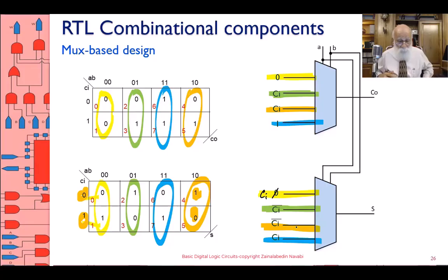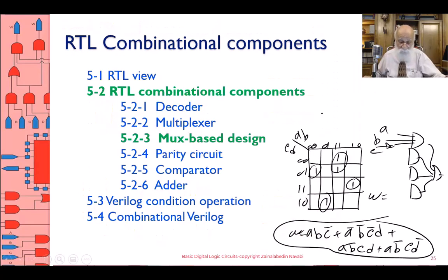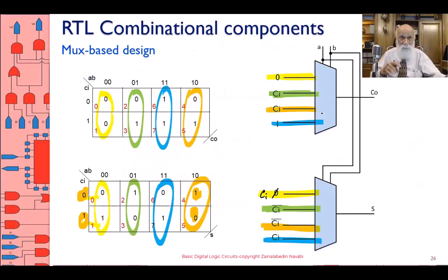So what did I do? Well, without having any extra logic whatsoever, I used two multiplexers, and these two multiplexers were used to implement the Karnaugh maps there. See, this is 0, 1, 2, 3, 0, 1, 2, 3. Just to mark these properly, 1, 0, 1, 0 for the most significant and the least significant bit of the multiplexer select inputs.